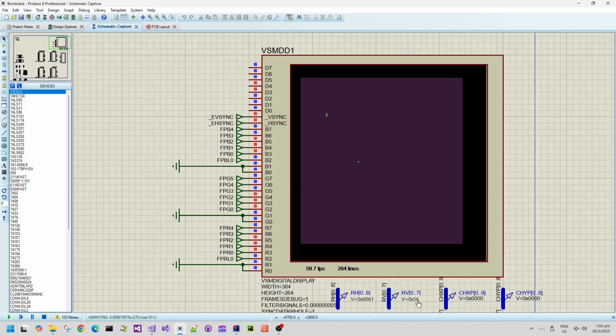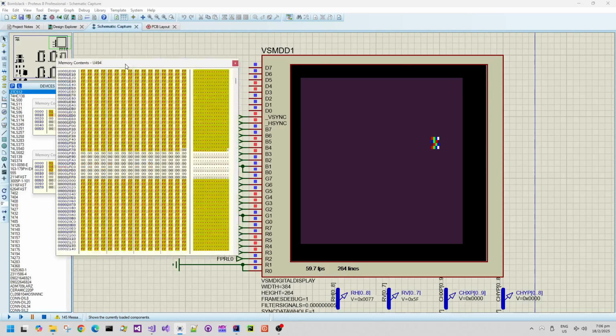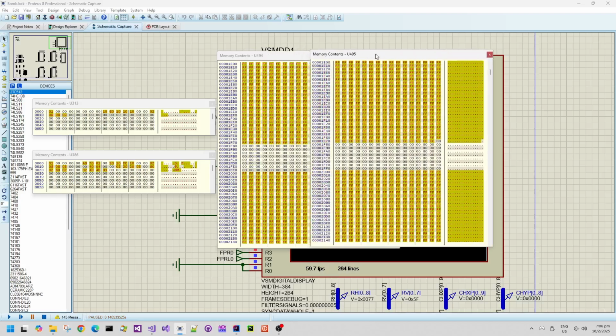And the specific ordering of those colored pixels tells me whether or not all of the address decoding logic, all of the sprite flipping logic, and everything else is working. The test then goes on and waits for a vsync, or vblank rather, and then updates the sprite coordinates just to check to make sure that the sprite can traverse the most significant bit in the x coordinate and then straddle the MSBX coordinate on the screen. The difference between 255 and 256 and 257 in the horizontal coordinate range.